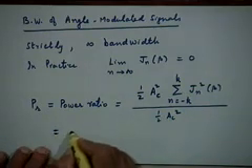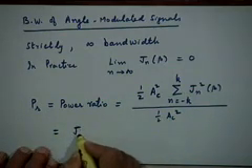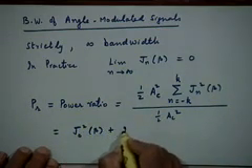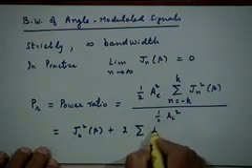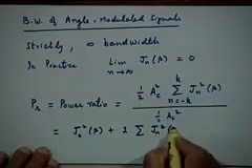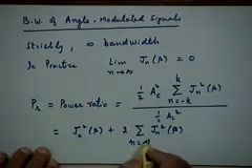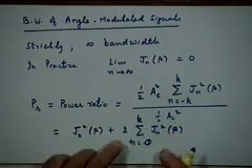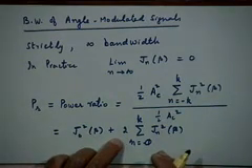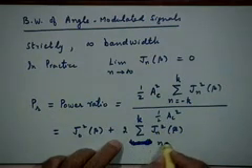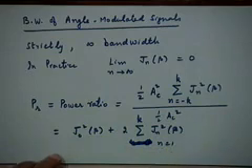So as you can see, this you can write as J_0 squared of β plus twice the sum of J_n squared of β, n going from 1 to k, because I have taken twice of this number of terms. I am sorry, this should be 1 to k, because 0 I have taken out. Thank you.